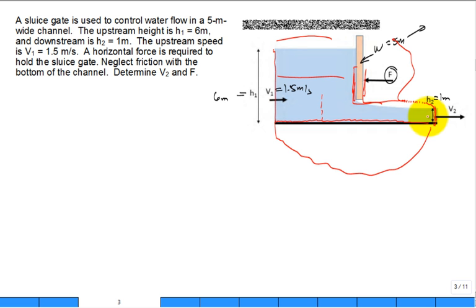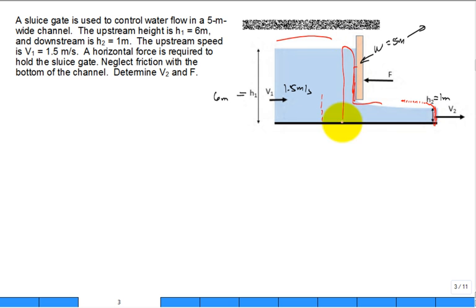It's really important here. A lot of people want to cut this control volume right in here, and then they come up into the air and they cut across the air and they come down. Or actually, a lot of people want to cut this control volume real close. Look, if you're interested in solving for V2, cut the control volume where V2 is. If you're given some information about V1, cut the control volume where V1 is given. Don't cut it over here and then assume, okay, I'm just going to keep on moving, there you go, I now know the velocity cutting over here. Well, don't do that. Why not just take the control volume to where you know information?